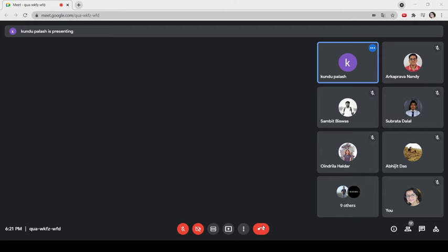But for timer 1, it has IT1, IE1, and TR1, which is the timer control for timer 1. There are other bits called TF0 and TF1, which are nomenclature for the timer overflow. I will describe them. So all 8 bits of the TCON register have different meanings. By setting or resetting each bit of the TCON register, it is possible to drive the timer in a different manner. The simplest manner is that we must set the TR bit for the respective timer, that is, TR0 should be 1 or TR1 should be 1. According to this block diagram, this functional diagram will appear for each timer, timer 0 and timer 1.